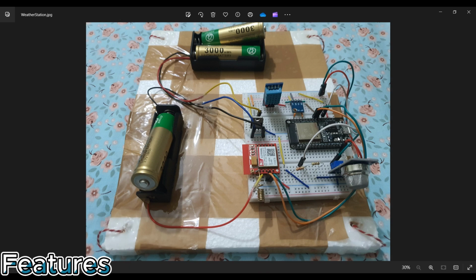So in order to serve that purpose, all you can do is simply use a pocket router and attach the pocket router on top of the board and connect the ESP32 board with the pocket router having internet connectivity, and following this way you can easily update all this information to the IoT cloud, to the IoT dashboard, and it doesn't have any kind of range related limitations, as long as the router is attached with the board. So as long as the network, like the 3G or the 4G network, is available, then the pocket router would be completely functional, and you would be able to monitor all this information in the IoT cloud dashboard.